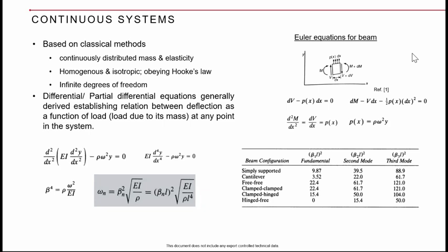So when you are trying to deal with a shaft modeling or a transmission shaft, for example, which is mounted between two bearings, and you want to avoid a certain whirling speed, I mean, you want to keep the frequency of your shaft above the whirling speed. So at the preliminary stage, a quick design can be done using these kinds of principles. You directly go and calculate natural frequency. I mean, what is your natural frequency requirement? You just put some margin over that and back calculate the cross section that you need to achieve that first natural frequency above a certain range.